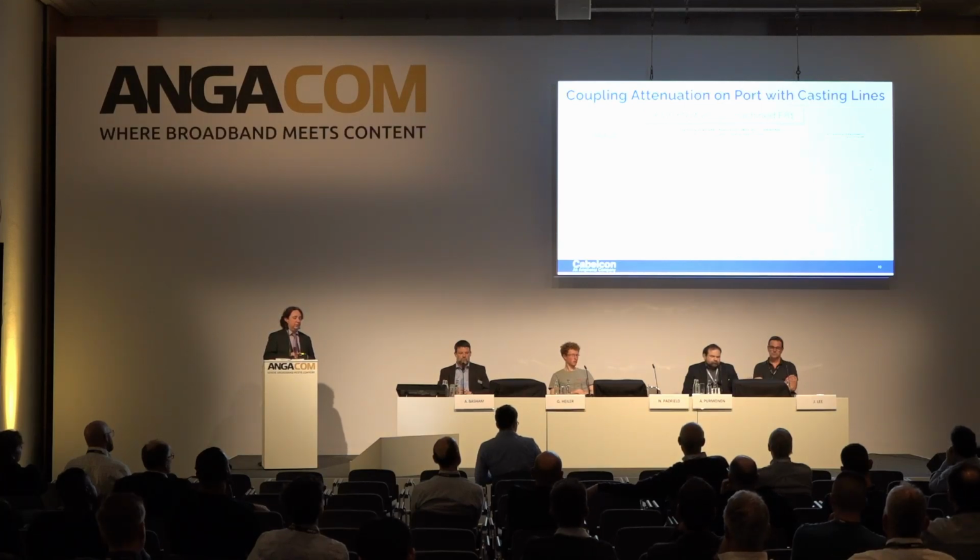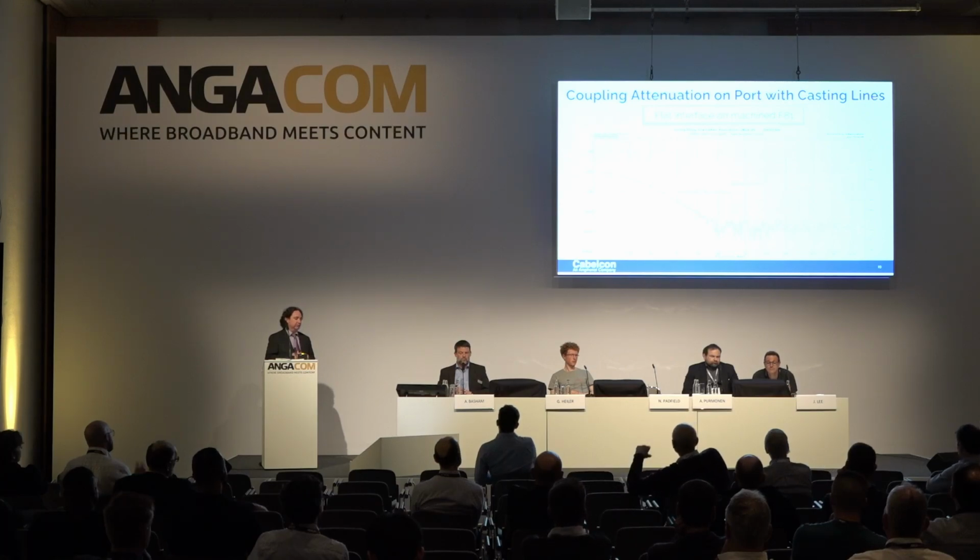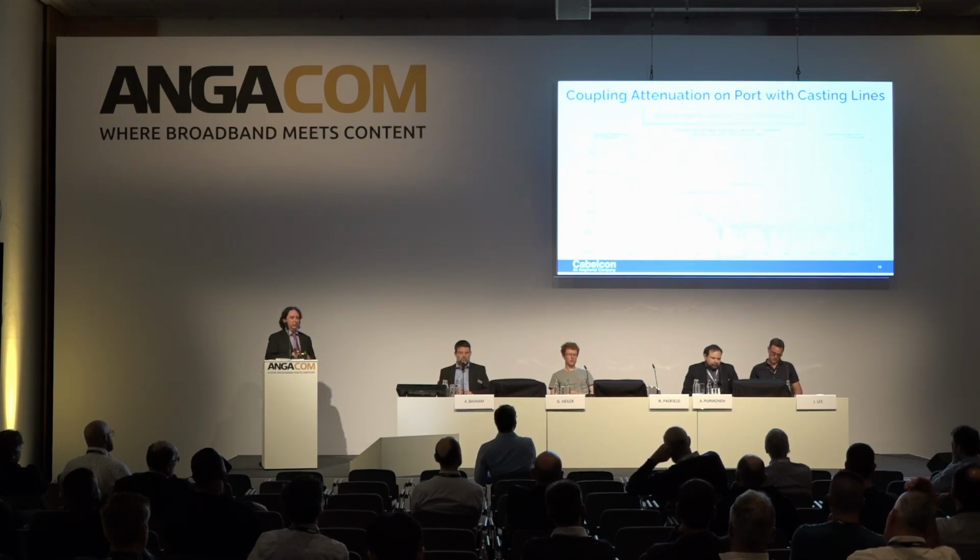Another thing we've done is quantify some of these things in terms of measurements on shielding effectiveness. Here we have the baseline of the measurement system, and here we have that interface with the high attenuation casting lines on it. So we're seeing that, even with the same connector and the same interface, there is a degradation of that performance. And again, using the same port but with the conical interface, we can show that we can get back to that baseline of a perfect connection.